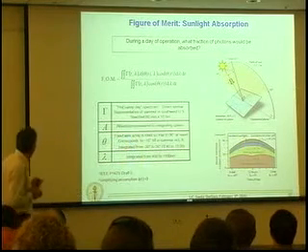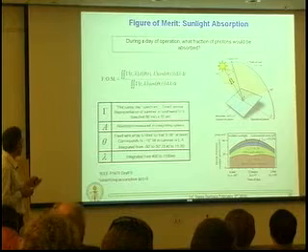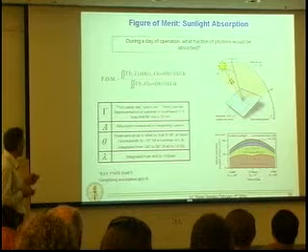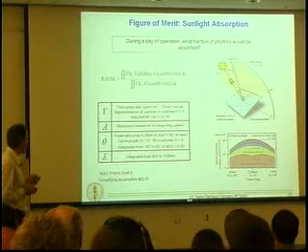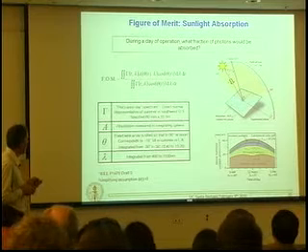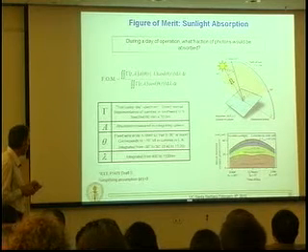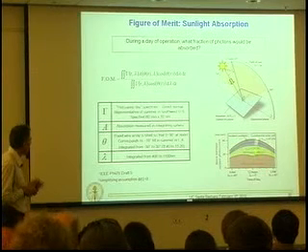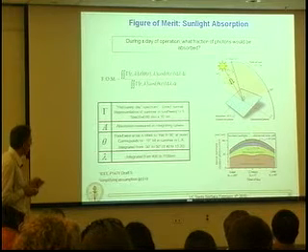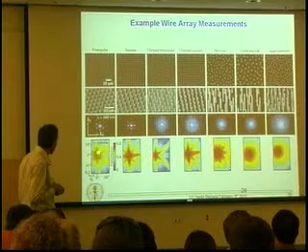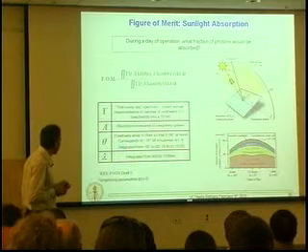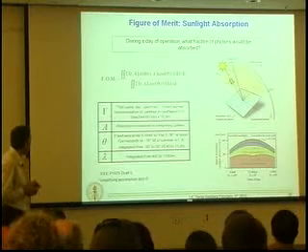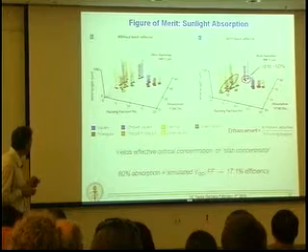So you can now ask yourself how much light would be absorbed in a single solar cycle, day-night cycle, if the sun were directly normal, under direct illumination conditions, and we integrate the energy generated in such a cell. And we can see that the array without a back reflector has a dip in its absorption right when the sun is directly overhead, when you have parallel illumination, because of this enhanced transmission along the wire axis. If we put in some sort of scattering structure, either a Lambertian back reflector or dielectric scattering particles, we can increase